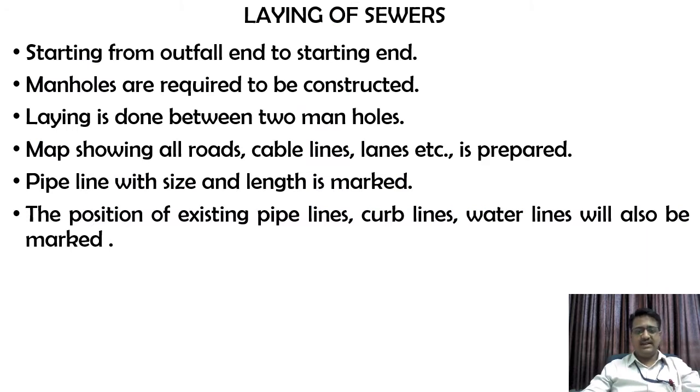Now, the next step of this will be laying of sewers. Okay, so for the laying of sewers, we need to understand a few basic steps. Okay, so we'll go through that. First, the sewers will be laid starting from the outfall end to the starting end. Okay, so the outfall end will be at the lowest elevation, and the starting point will be at the highest elevation. So based on that, you are going to decide the slope of that particular